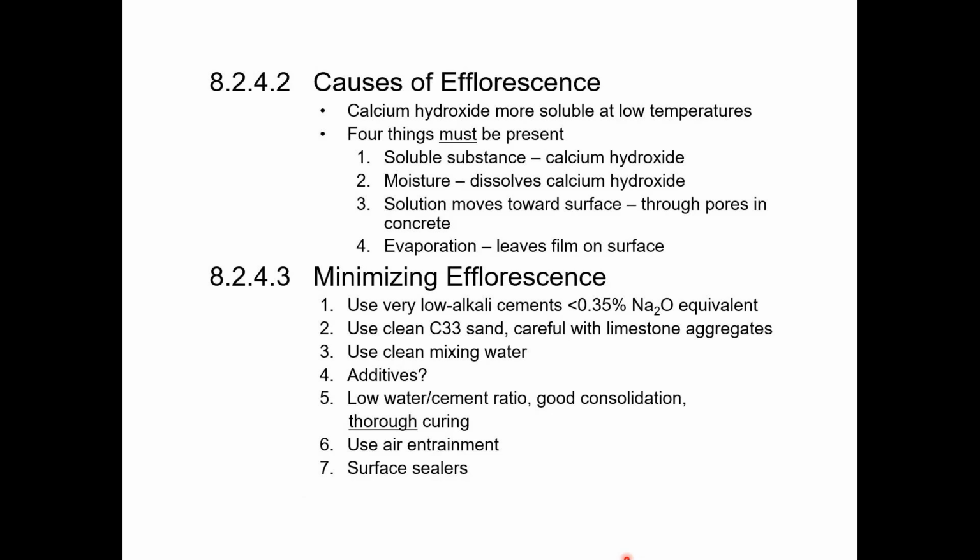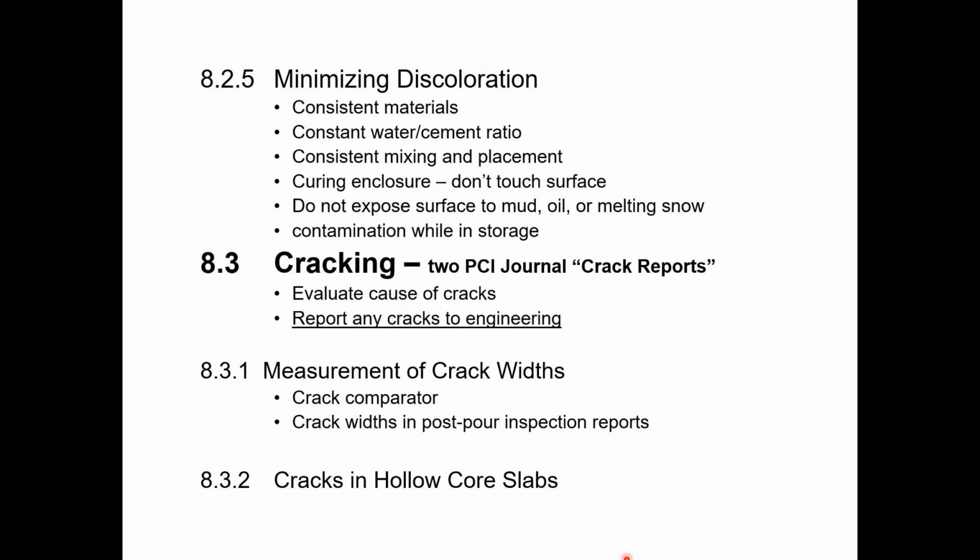Okay, so let's move on from efflorescence then, and let's continue talking about general discoloration, not necessarily discoloration caused by efflorescence, but discoloration that could be caused by any number of other issues in your plant. So we want to make sure we're using, we've said it before, I'm saying it again now, consistent materials. Make sure your aggregates are regularly mixed and blended so that you're getting a good distribution of particle size, shape, and color. Make sure you have a consistent water cement ratio.